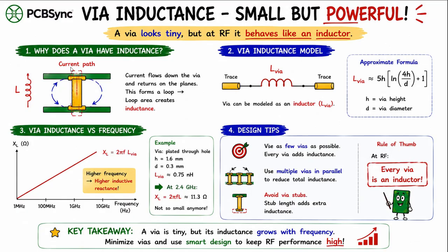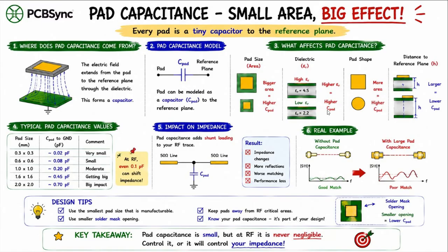A lot of people think vias are just holes for passing signals, but for RF engineers, the first thing that comes to mind is inductance, because as soon as current flows through, it has to complete a return path, and that return path creates higher inductance. The problem becomes more obvious. So there's a saying among RF engineers: every via quietly adds a bit of trouble for you. It might not seem like much, but when there are enough of them, they'll gang up and cause you real issues.